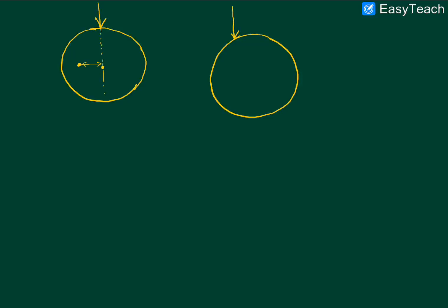Well, in this case, most of you can intuitively understand that there should be some kind of twisting induced in the beam because of this force. So when we say that, what we are intuitively doing is taking the torsional moment of this force about an axis which is going into the plane and which is passing through this centroid. And that would be absolutely correct, that the torsional moment is indeed non-zero.